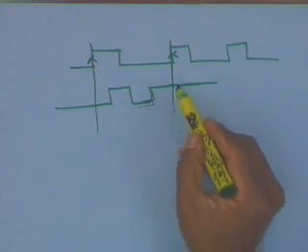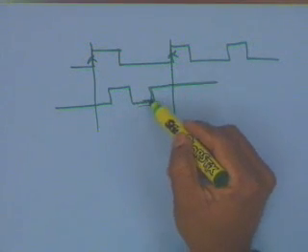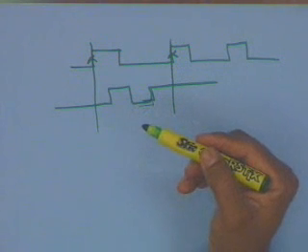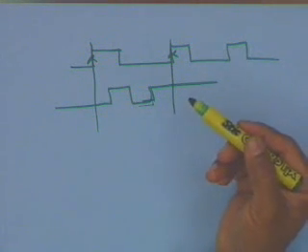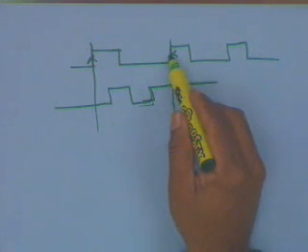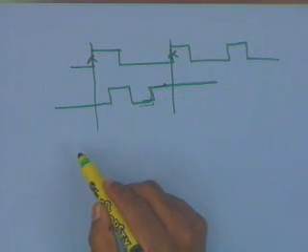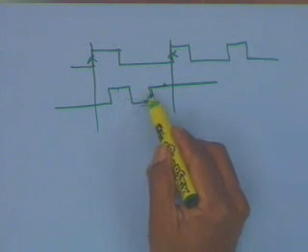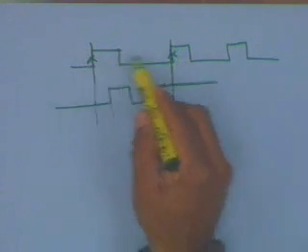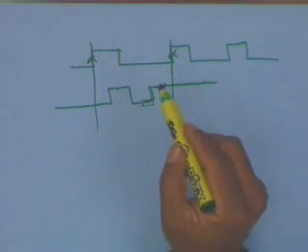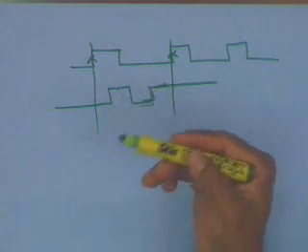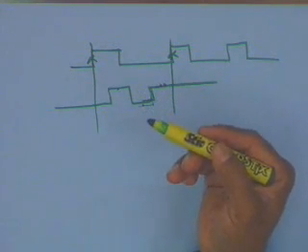Temporarily the outputs may change, but these input changes are not going to be captured in terms of the state of the machine, because the state transition is only going to occur over here and it is only going to sense that it is actually 1 over here. The fact that it was 1, a 0 and a 1 is going to be completely ignored, because all of this happened within the clock period. So that is the typical model of a synchronous sequential machine.